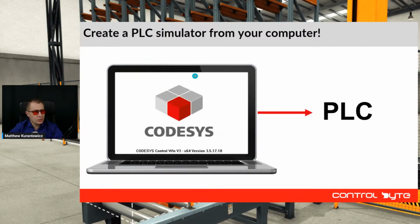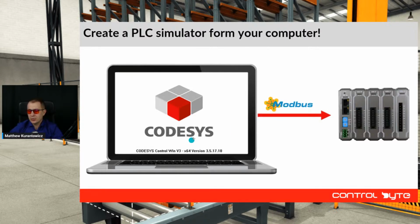Okay, what you need to do is to download a CODESYS environment on your PC, on your laptop, and you can create a PLC simulator from your laptop and test your programs. You can also communicate your PLC simulator with external devices like remote IOs and even external simulators.